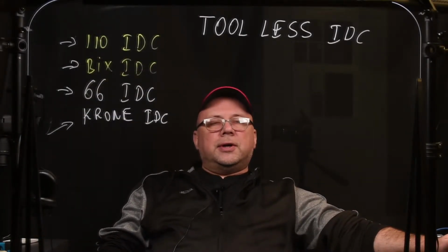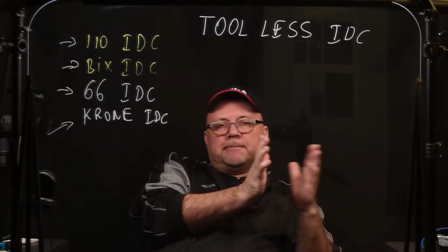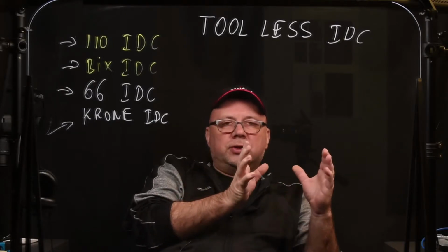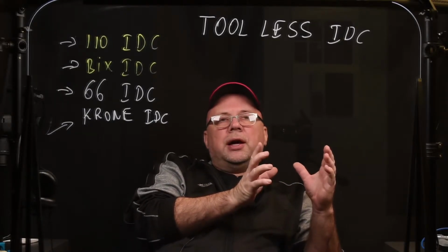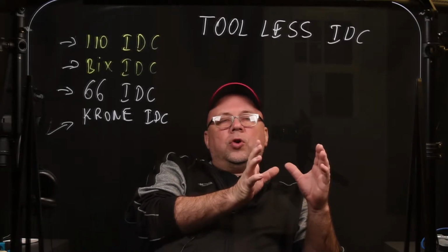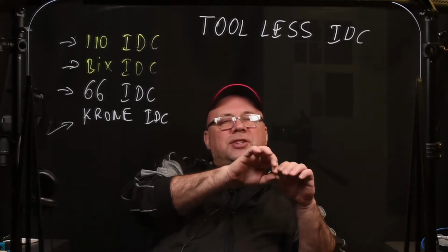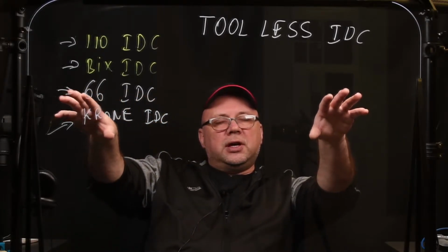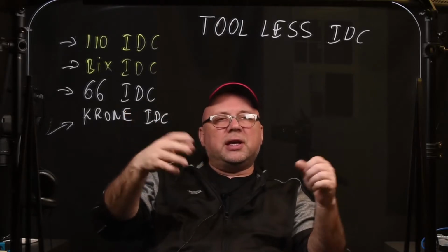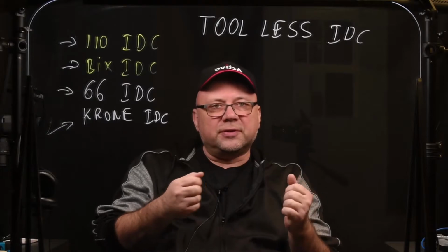This would be a rack location where everything home runs into the communications room, and the field wiring comes out of this communications room or home run location. It branches out to the field, and the field is the building, the rooms, the offices, the desktop locations, and so on. So that's considered the field wiring.